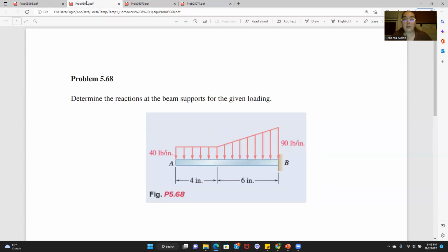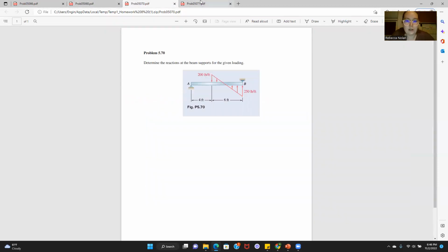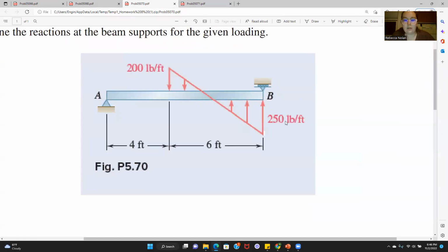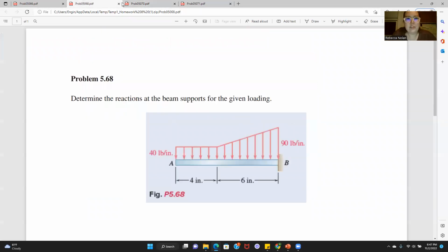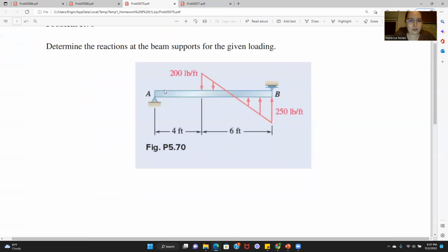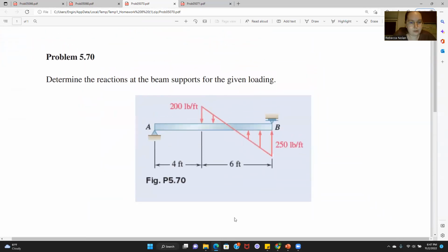So like a roller, if you had a roller on the y-axis, so B is going to have a degree of freedom along X and a rotational degree of freedom. The y-axis is constrained, so there is no freedom there. Just to kind of introduce a little extra verbiage and whatnot.